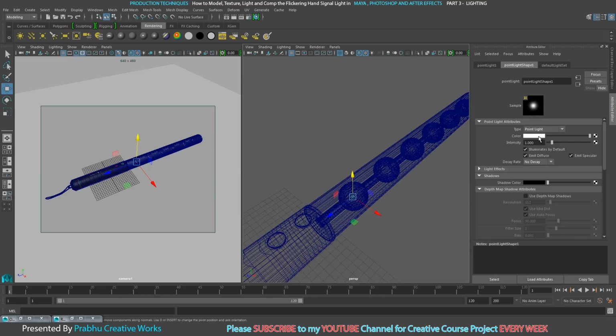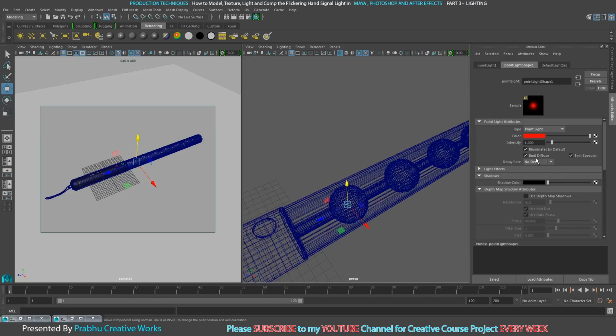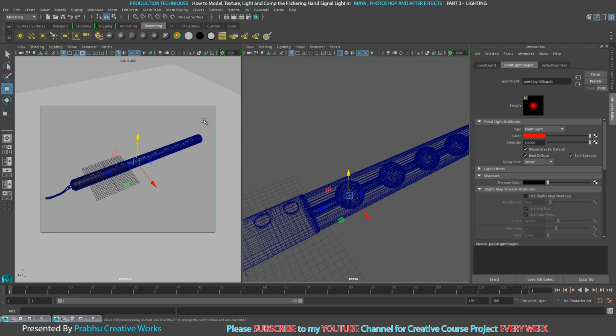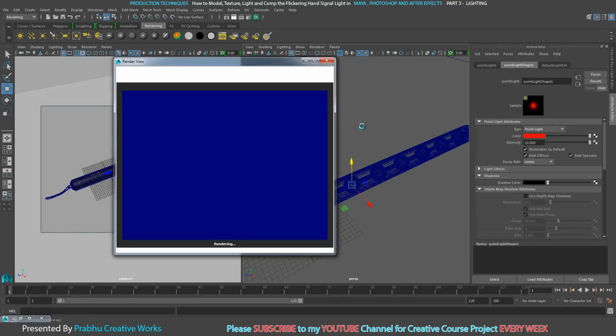Now I want to change my point light color to red. Now I want to give some decay rate, otherwise it will infinitely flow the light. So I want to give linear decay, give intensity to 10 or something. So now I want to check this one, so I will click this viewport. So in perspective I will check in close.